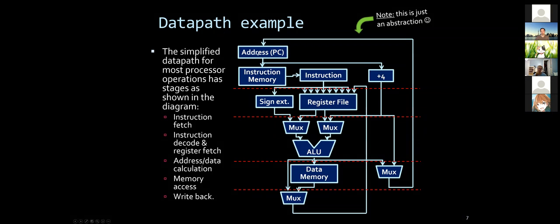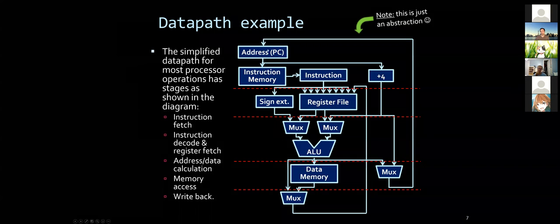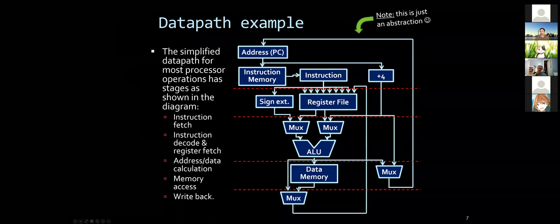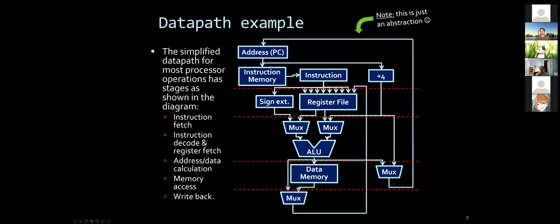By this address, I can read the instruction from the instruction memory, and that instruction has the next steps on what to do. And in parallel, by reading this instruction in the first step, I also want to point the instruction pointer to the next instruction. By default, it's just adding 4 bytes, because the next instruction is the next 4 bytes. We'll go carefully over that.